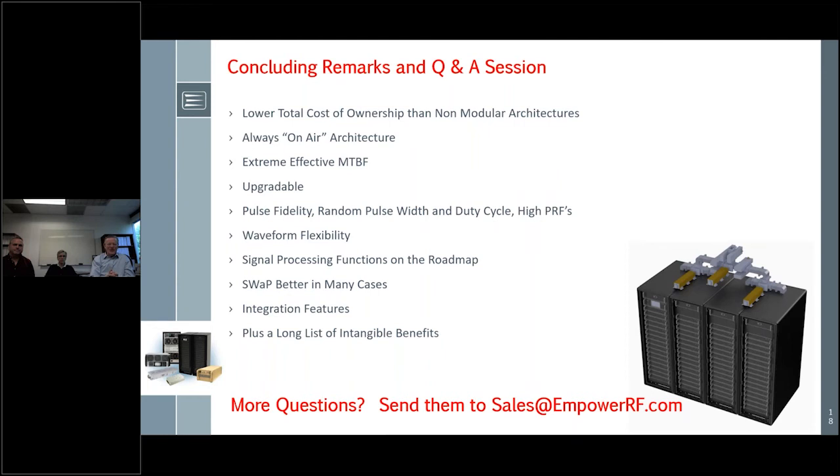And certainly we're not here today to say that the world is over for TWT solutions. It's all about solid state. There are practical considerations, size and power density, particularly as you get higher in frequency, where a tube-based solution certainly still has legs. And I think from my perspective, if it's on a fast mover, on a drone, those sort of concentrated power requirements, this architecture does not lend itself as well to that.